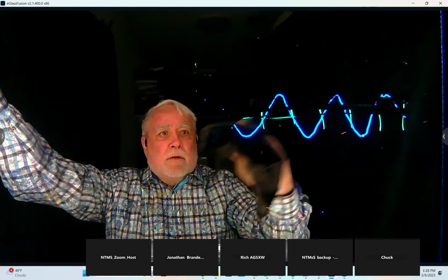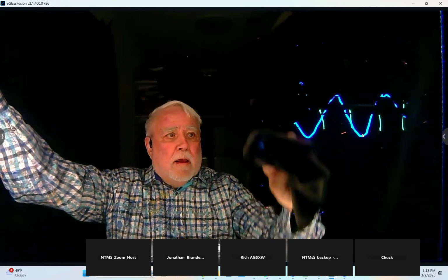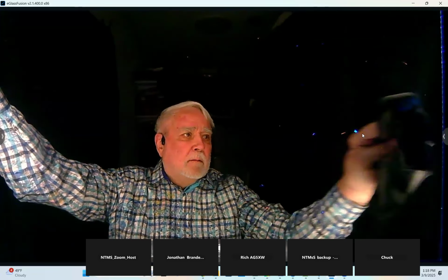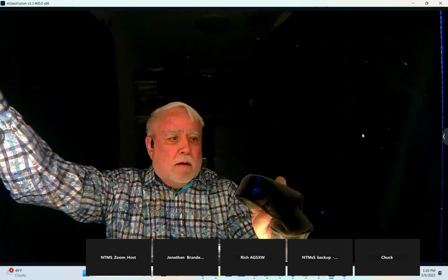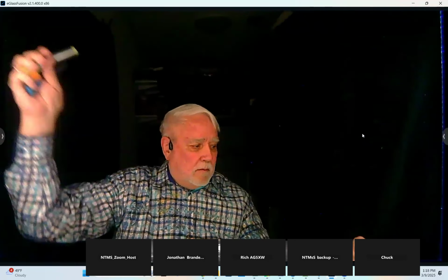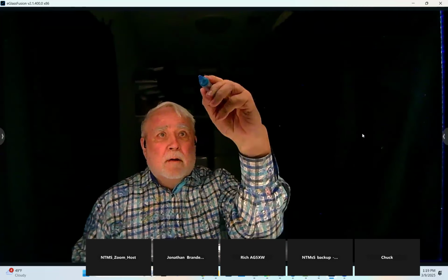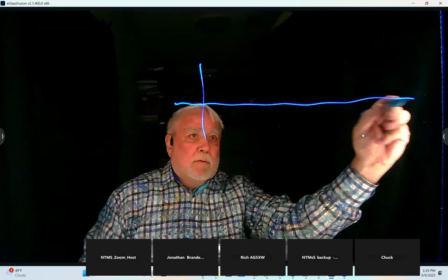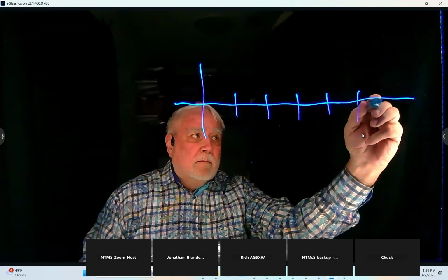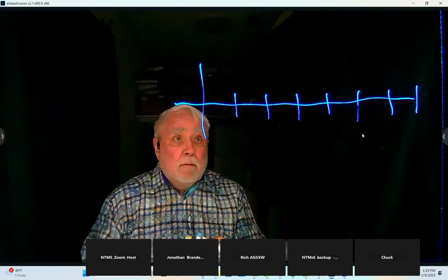Now let's raise the sample rate to 1.5 times and look at that one. And you can definitely simulate this in your GNU Radio and see the problem, because all kinds of bad stuff happens. Okay. Once again, we've got time, a different color, but 1, 2, 3, 4, 5, 6, 7 divisions of time. I've got a signal.